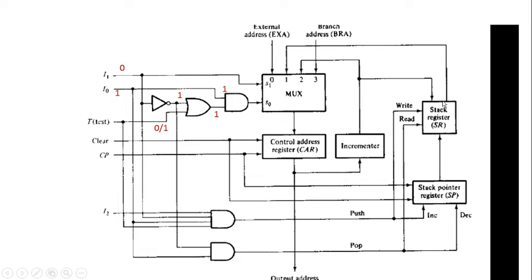After completing the subroutine execution, now the control wants to go back to the main program. In order to come back to the main program, we want to fetch or pop the return address from the stack register file first, then jump to that particular location in order to resume the execution of our caller program.